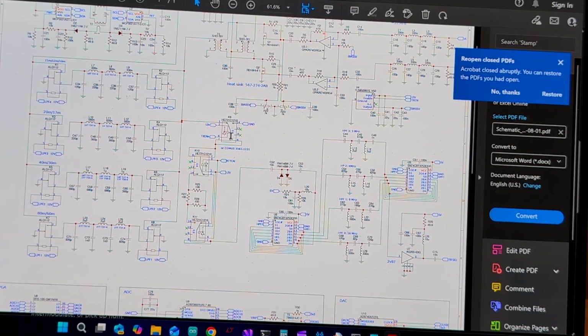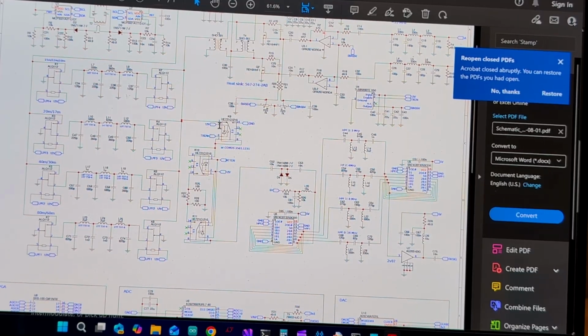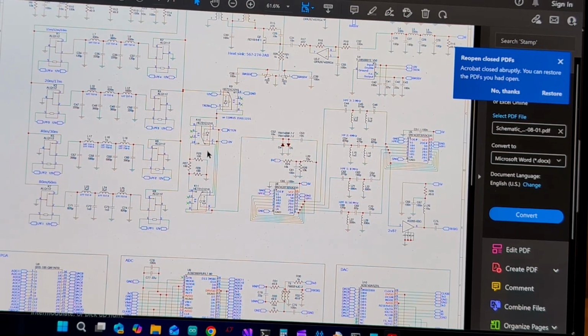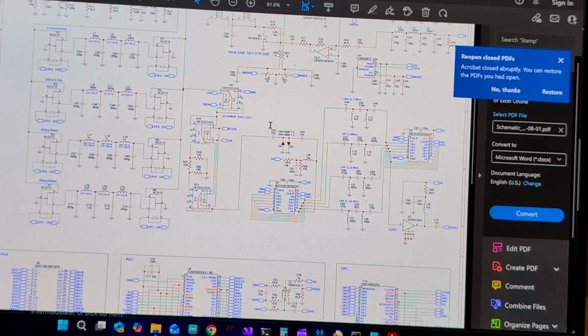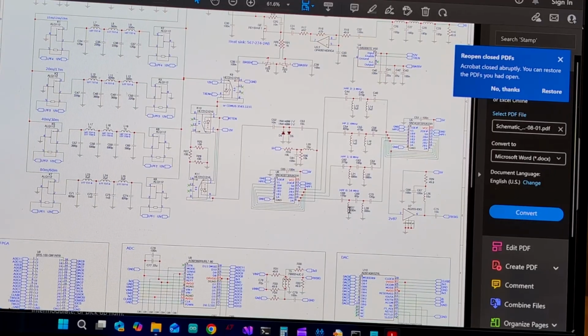It's a reed relay. Really like reed relays, they operate silently and within 2 milliseconds. Then I've got a 12 dB attenuator here through some large signal suppression protection, and now I've got some switchable high pass filters here.